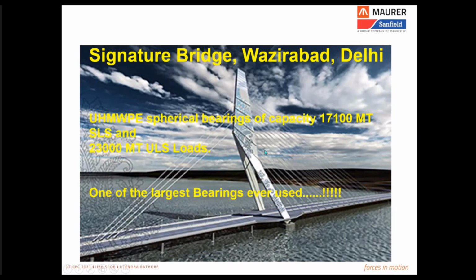And this is a cable-stayed bridge. There are two big bearings at the base of this pylon, which is holding the entire main span. And each bearing in this location is designed for 17,000 tons service load and 23,000 tons ultimate load. And you may not be able to appreciate what 17,000 tons of load is all about.